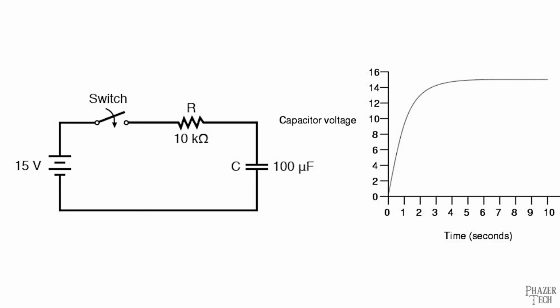Likewise, if we swapped it for a larger capacitor of, let's say, 2200 microfarads, then it would take longer to charge up to 15 volts. This is because larger capacitors are storing more charge per voltage than a smaller one is. This means that if they were to discharge, then the larger capacitors would be able to provide more current for that given voltage. But they aren't able to react as quickly to sudden changes in voltages compared to smaller capacitors.